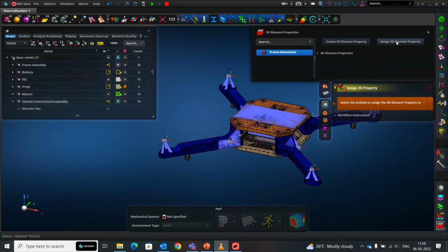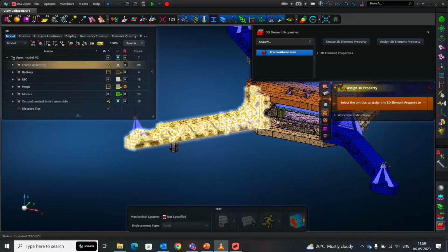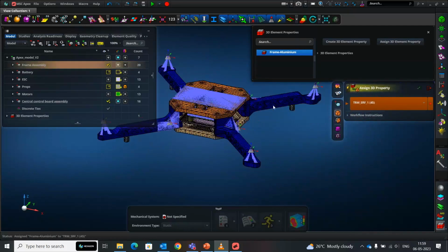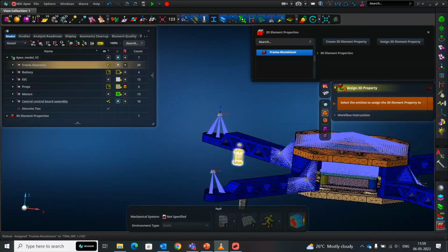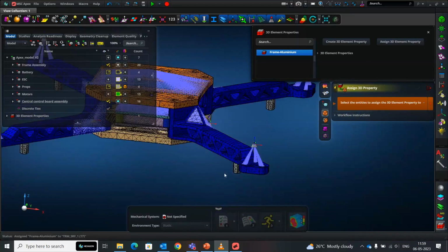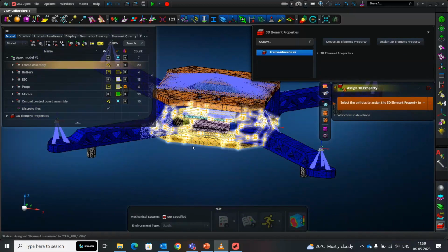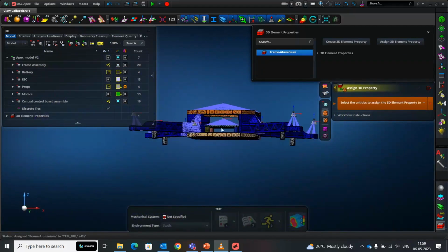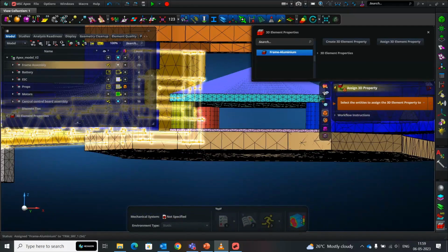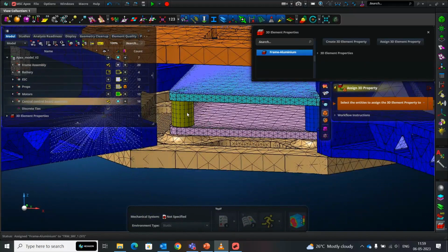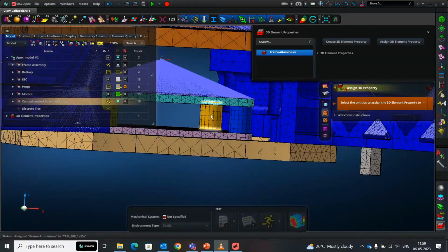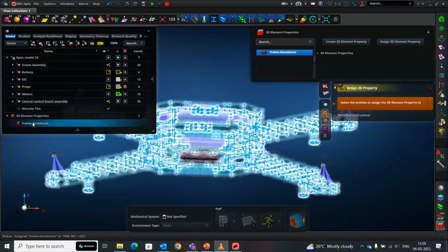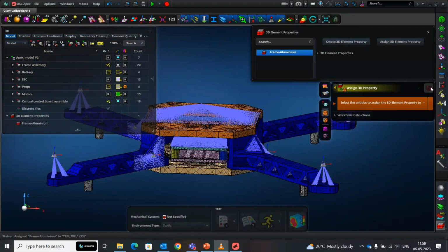So I'm going to choose the solid property aluminum, and I can assign it to either parts, solids, or cells. I'm going to choose solid bodies, and as I wish to assign it one by one, I begin to assign aluminum. So I'm just saying my entire frame is aluminum, and that's my base, that's my top, and then my spacers are also aluminum. So I choose these 4 spacers as well. Need to be careful not to assign it to the boards because they are PCB boards. So only the spacers are aluminum. Now the material application is completed. So just like that, I can assign the material.